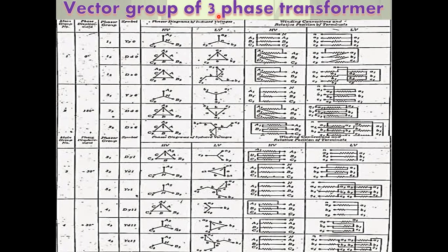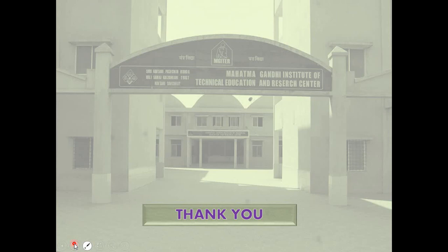For three-phase banks of single-phase transformers: first is delta-delta, star-delta, and delta-star connections without neutral wire or neutral grounding; third is star-star connection without neutral; and fourth is star-star connection with neutral. Second is three-phase transformer units. Okay, so harmonics also depend on the three-phase connections of the three-phase transformer. Thank you.